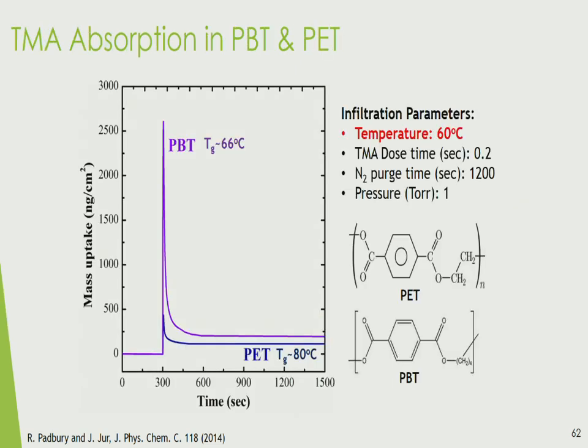So then we can start changing some of the polymer components, or the polymer backbones and the polymer functional end groups, within the same polymer series. And this tells us more information. So this is the TG of these two polymers, PBT and PET. You'll notice that the repeating unit is a little bit longer here, by two CH2s, than the PET. We actually get a much higher increase.